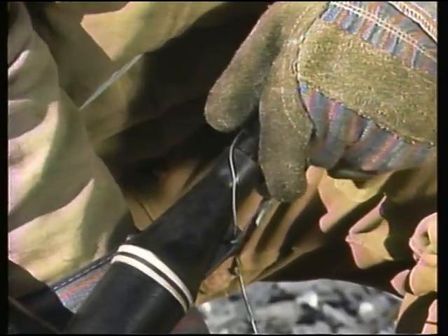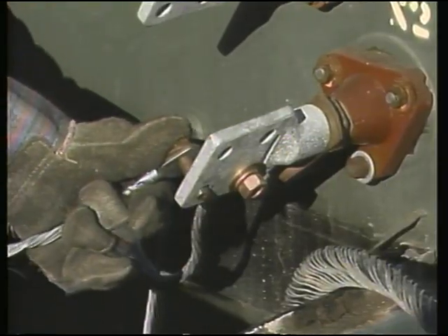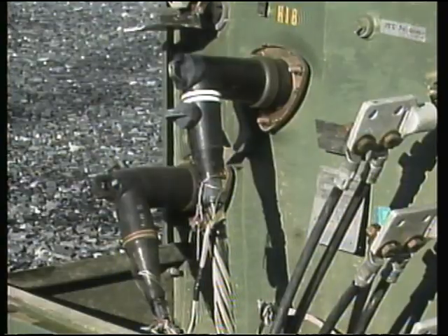This is done by taking 2 strands of the concentric neutral wire and feeding them through the grounding eye of the elbow. The cable's concentric wires are then connected to the grounding lug, which is connected to a known ground source. This grounds the outside layer of the elbow and completes the termination.